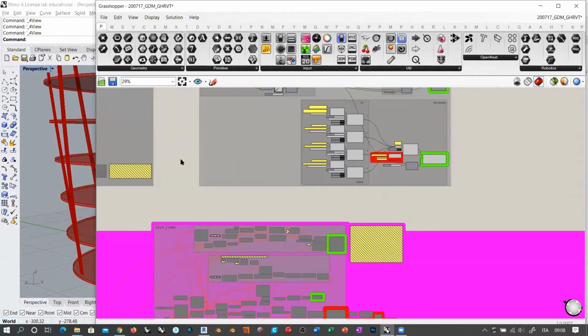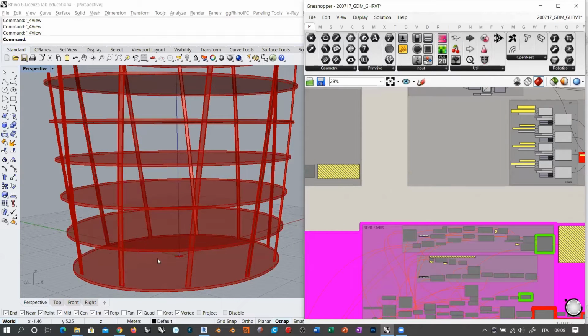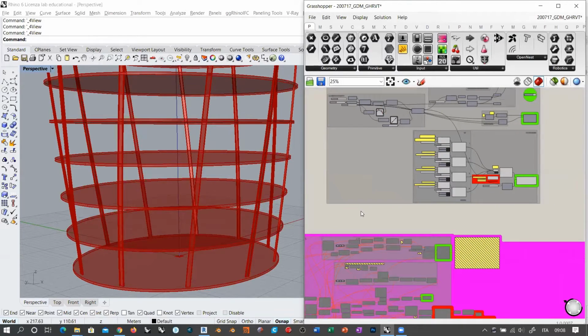In Revit, when you have stairs connecting several stories, several floors, you can create a void volume that simply cuts a hole through every floor, and therefore it allows placing the stairs correspondingly in a good way. This feature was not working. Now it is. So now you can easily create shafts and voids inside the floors in Grasshopper, and they will be recognized by Revit as shafts. So it's pretty nice to have this feature.